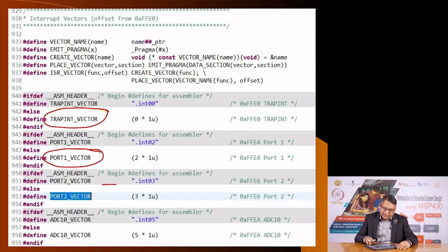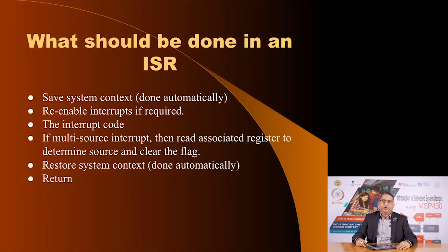We will illustrate it with an example. Now, what do you do? What happens in an interrupt subroutine? Well, the moment the main program is interrupted, you must save the context. And what do I mean by the context? Context is reflected by two things, the status register plus the program counter. So, both these registers have to be saved, so that you can resume, using the values here, whatever program was interrupted. This is done automatically by the microcontroller. How? It saves these two registers on the stack.